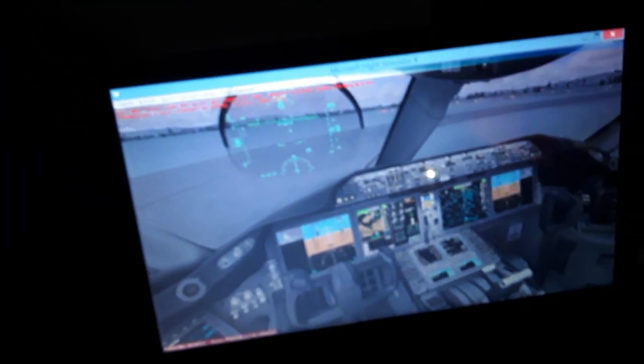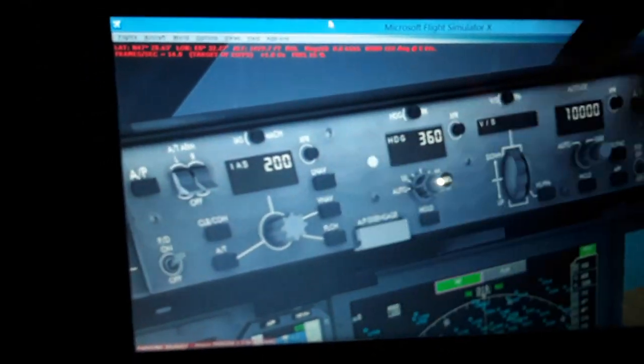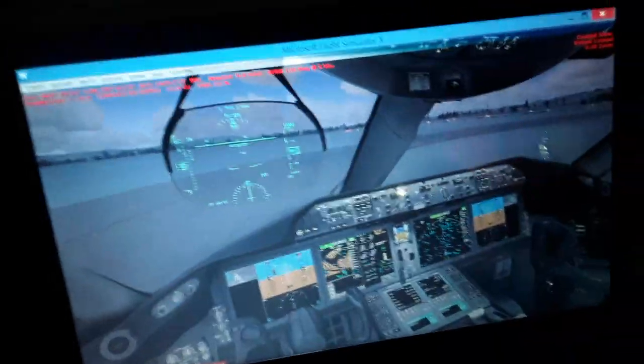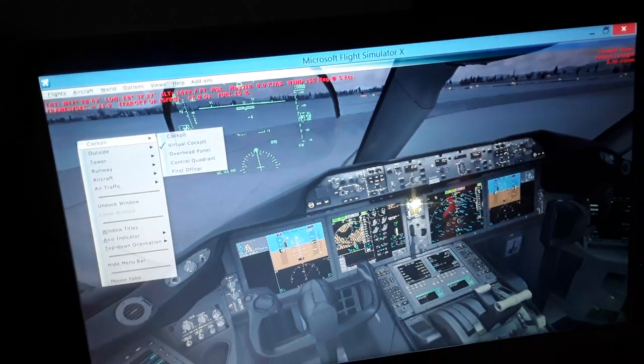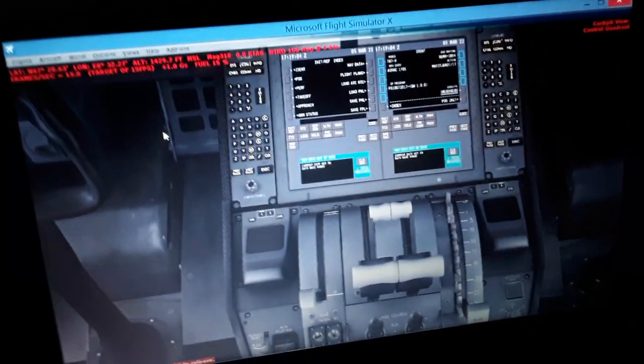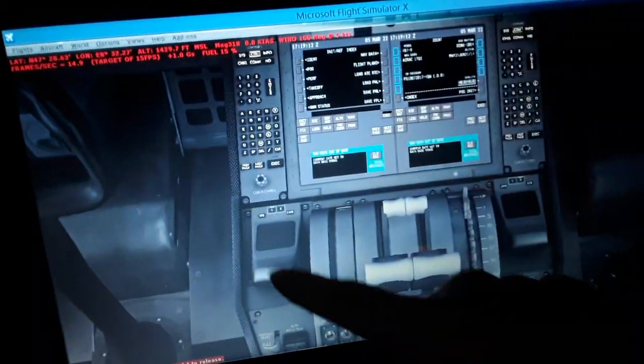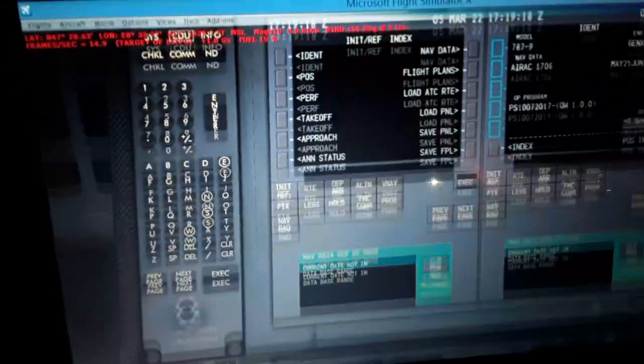You're gonna see how we're gonna do that using the flight management computer. We're gonna have a complete route of flight path or flight plan, so we can use the flight plan. Also it is interconnected, as you can see here later, with the LNAV and the VNAV function of the autopilot flight director system panel. It takes the inputs from the flight management computer over here. So we're gonna use this control quadrant over here. You can see we have the mouse pad here that I told you. The mouse pad is here, the keyboard, and the functions of the CDU, the control display unit.